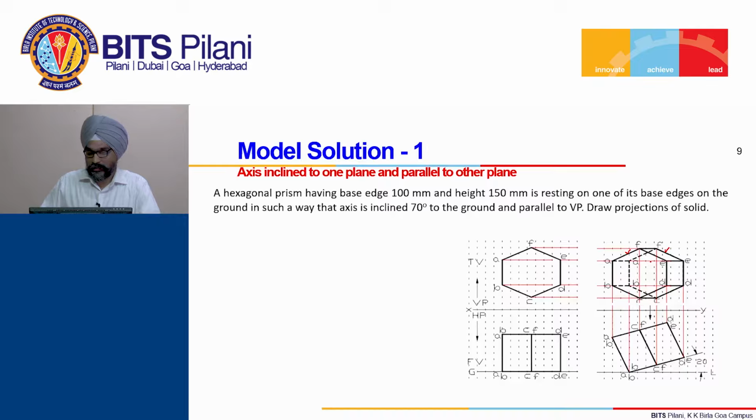In addition, you can see from the top base to the bottom base the corresponding points are connected, but from A to A, this point is connected but hidden, because this is at the top, and the one which is here is the bottom base. So, part of that is not visible. So, the vertical edges also will not be visible. So, this vertical edge will also not be visible.